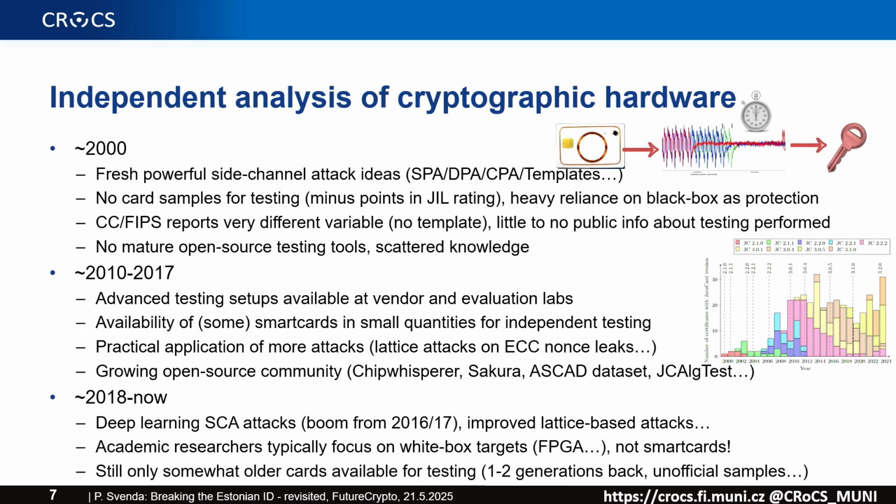I'm suggesting this protection, I'm implementing it, I'm measuring it again, and showing that you need 100 times more traces. So it's way more difficult to attack. You want to have a controlled way, right? So you are working with maybe an FPGA where you implement everything, but basically that's a white box target. Not that many people were working on the black box ones, the real smart cards.